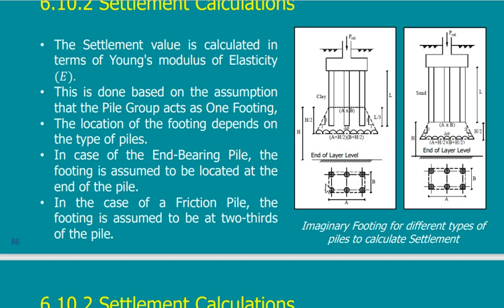So to calculate an approximate method, I just go to h divided by 2. If this is h, I take the middle of the layer and calculate the stress at the middle of the layer. How to calculate this stress? The same load, but instead of being divided by A by B, I will divide it by A plus h over 2 and B plus h over 2.